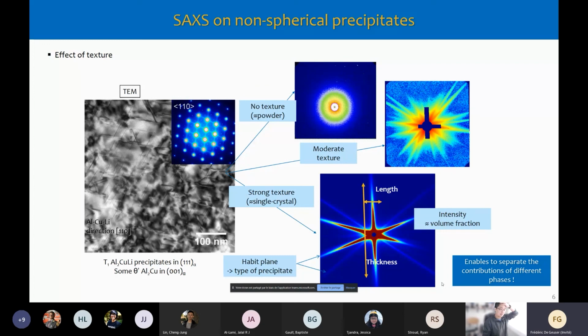Okay. And what's the pixel size for this scanning of this diffraction? So here, this is not scanning. This is a single image. What you do is you send your beam on your sample, so your analyzed volume is the size of your beam. The size of the beam is about 100 microns or less at a synchrotron. In the lab, it would be more like 1 millimeter. And if you want to do it with neutrons, it will be more like 1 centimeter. So that really depends.